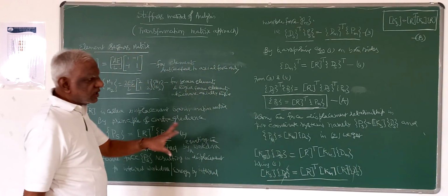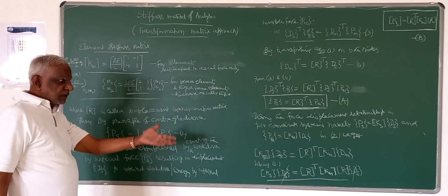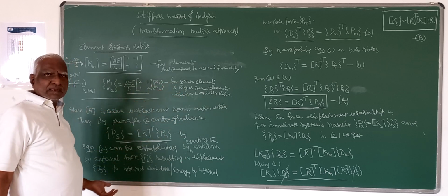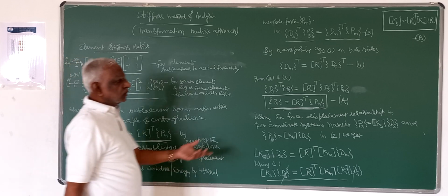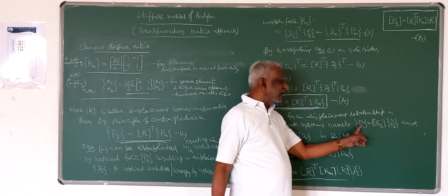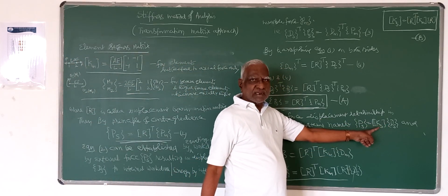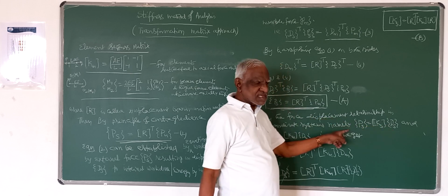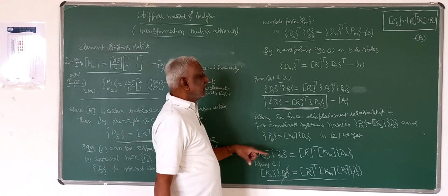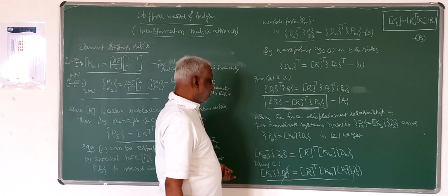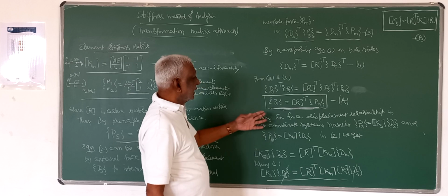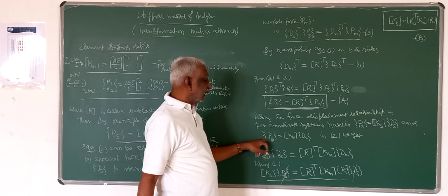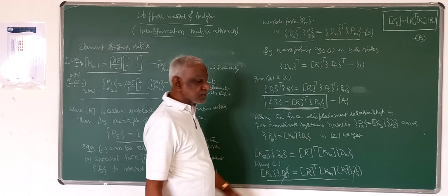Because analysis involves determination of displacements due to the given loadings, as well as the internal member forces. So the displacements due to the given load, after determining Ks, you can determine using this relationship, and then the internal member forces you can determine straight away from the relationship between the internal member forces and the displacement.